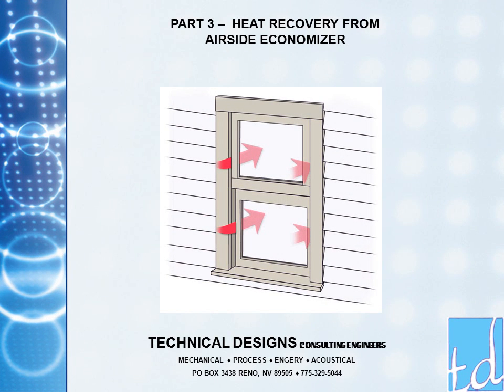Another aspect of heat recovery is using the airside economizers. In each of the classrooms is a CO2 sensor. The function of the sensor is to make sure each classroom is receiving enough ventilation air. Because of the occupancy, classrooms require a lot of outdoor air. Conditioning this air is an expensive proposition, and most times it's just exhausted out of the building.